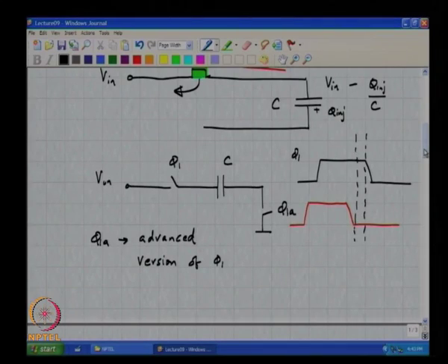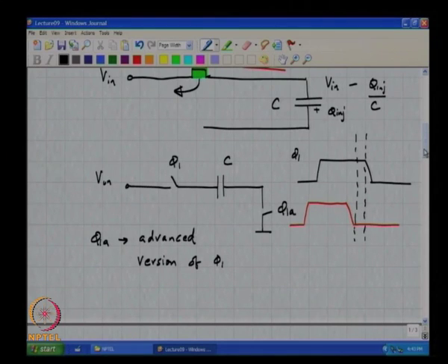Yes. So in the bottom transistor, the charge is fixed. I mean, it's independent of Vn. But the fraction of charge that is going into the C, why should it be constant? It turns out that it depends only on the ratio of the impedance it sees here on the left to the impedance it sees on the right. For one, the impedance it sees on the left is very, very low because it's ground. So most of it will go to the left, a small amount will go to the right, and that impedance remains largely fixed, regardless of the input.